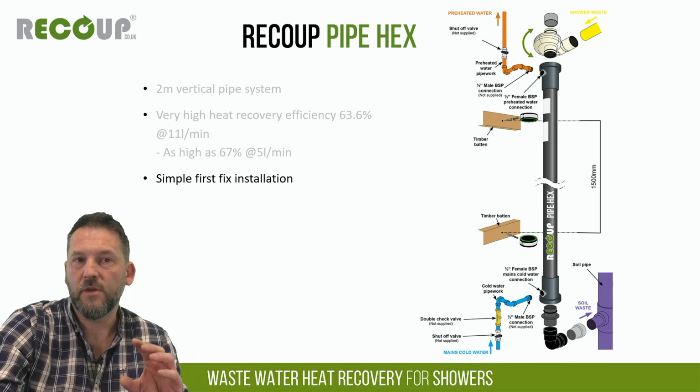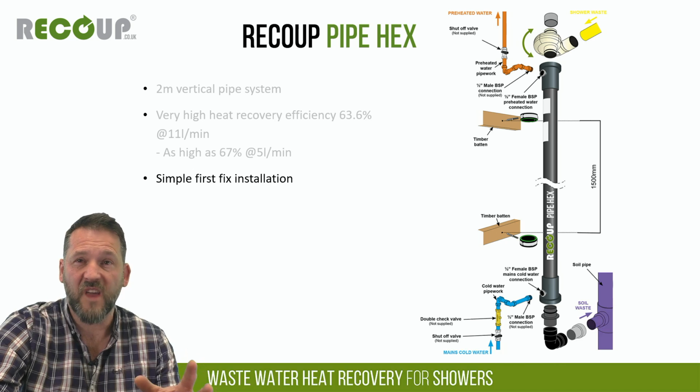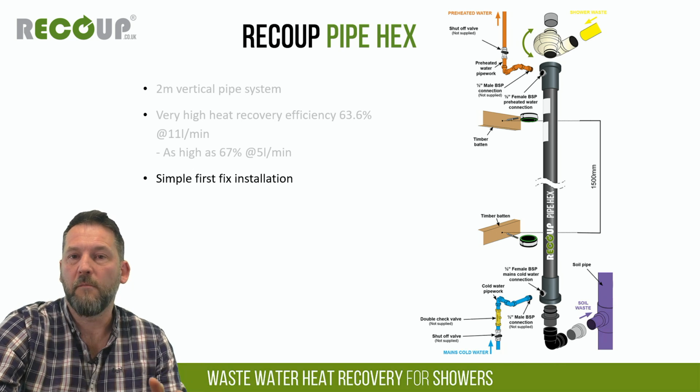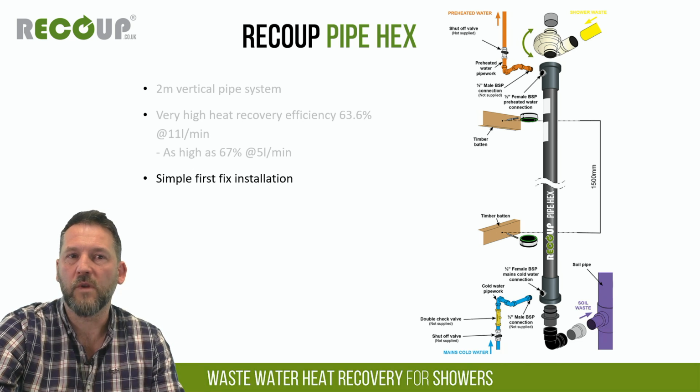In addition to what we supply as a product, so the heat exchanger and the installation pack, all that's required from an installer is usually just a double check valve on the incoming cold water main, 2 isolator valves, and then 1/2-inch BSP irons for connection. So that can connect to 15mm pipe, 22mm pipe in most cases, but that will be specified. It really doesn't take a great deal of extra plumber's time or materials to install wastewater heat recovery. Usually installed at first fix, normally 1 to 2 hours of extra plumber's time.